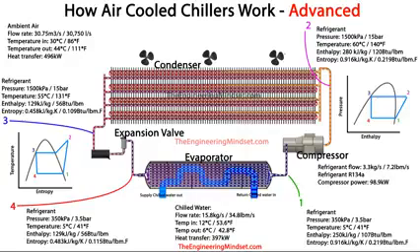And the temperature coming out of there, once it's given up all that unwanted heat into the evaporator, and that refrigerant has taken it away off into the compressor, round into the condenser, where it rejects that heat and comes round. So by the time the chilled water leaves the evaporator to go off around the building again and collect that heat, that should be around 6 degrees Celsius, which is about 42.8 degrees Fahrenheit.